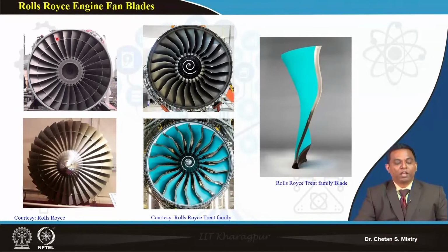Now when I have my inflow condition, we may have different kinds of inflow: it may be smooth flow, or it may be distorted flow. By distorted flow, I mean there is a variation in pressure, temperature and total pressure, there is a formation of wakes that will be striking, and atmospheric turbulence goes inside the engine. All these things create disturbance in the flow going inside.